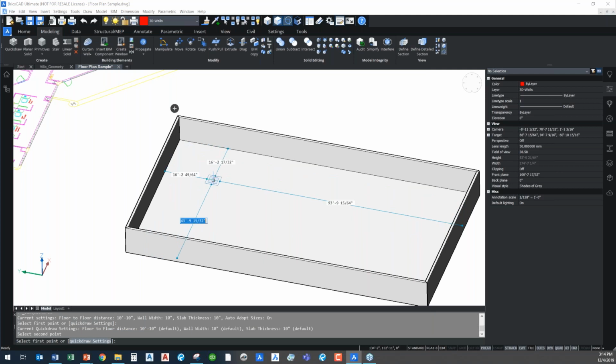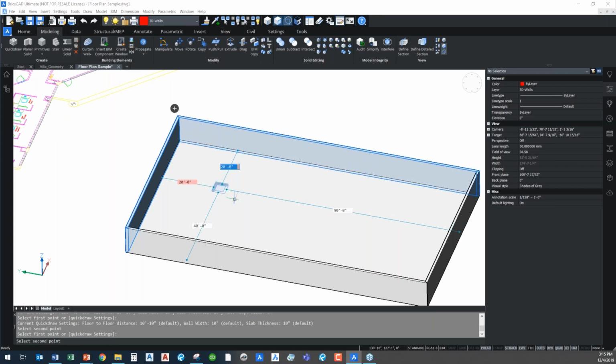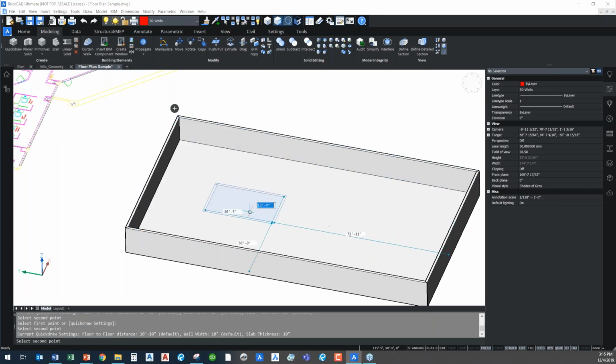So you kind of see right here where I've got this 16 feet 2 on each side. I can adjust those. See, I can tab to where my next wall is going to be, right? So I can bring this wall out to 20 feet by 20 feet, and then when I hit enter, that's where my next wall starts. So you say I started from that corner 20 feet over, right?